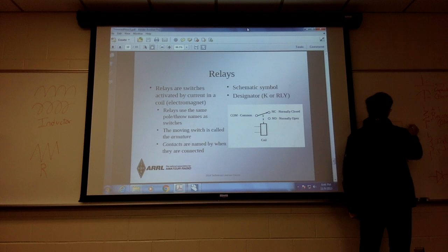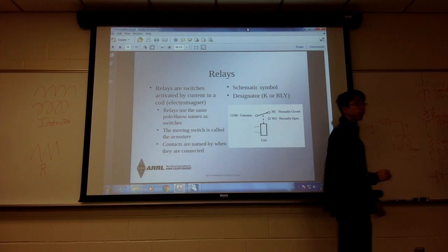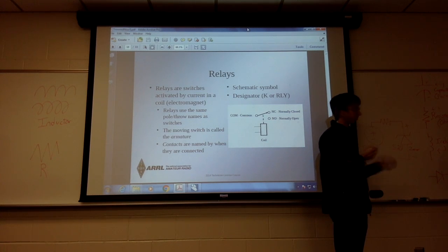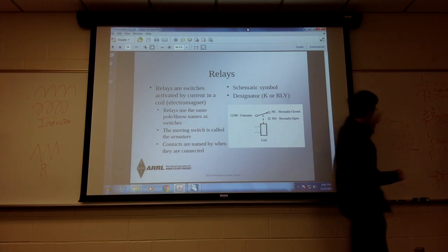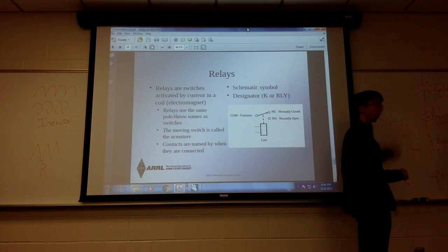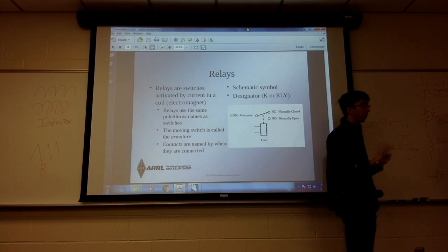What is going to be the voltage across the Zener? We've got 12 volts across our voltage source, and some resistor here to limit our current. As long as this is greater than the breakdown voltage of our Zener, we're going to end up with 5.2 volts across our Zener, within limits.